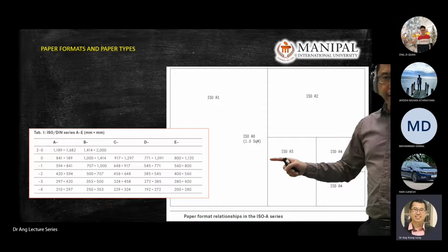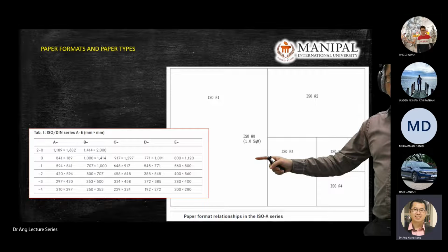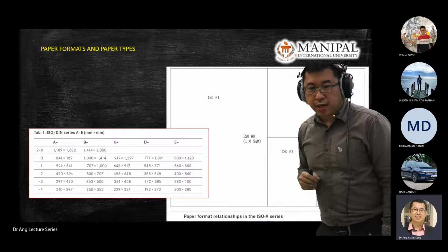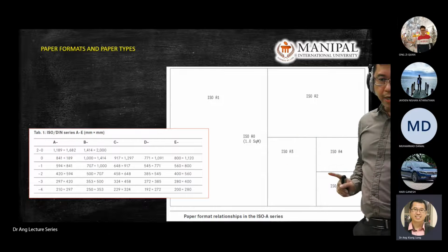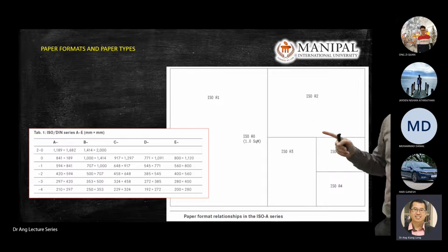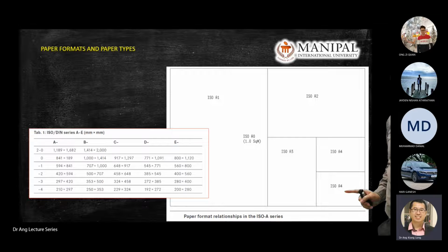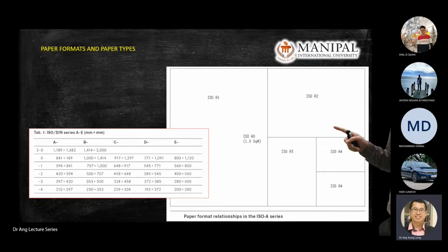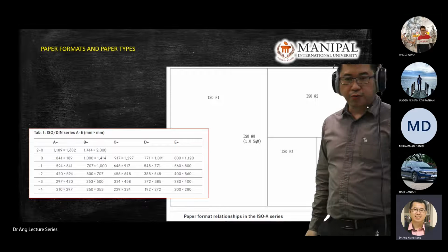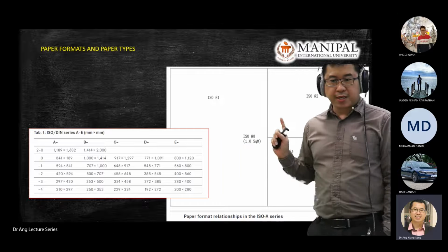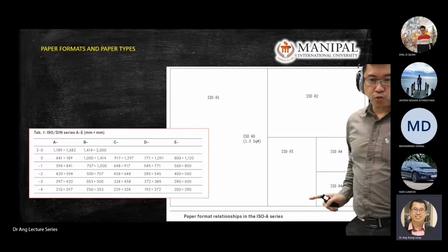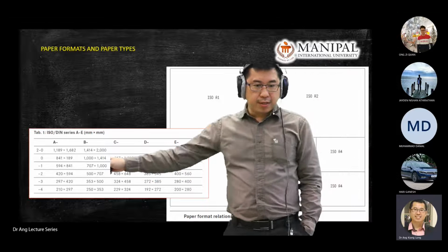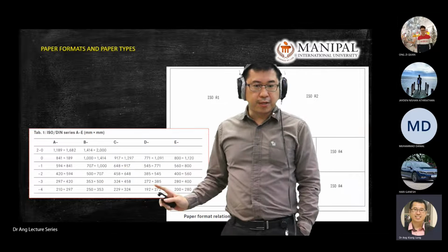Be careful on your technical drawing. You might be using A1 or maybe A2 in your software, when you submit your report in A4 size. So just be careful on the conversion of scale from here to here in your software. Right, you need to do some setting from here to A4. So these are the size of the paper that you can check from the slides here.